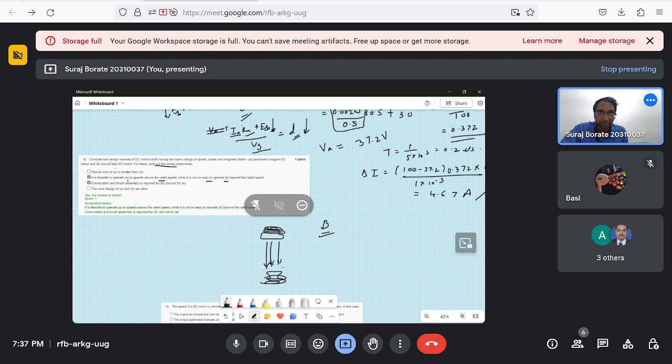There is also something called peak current and peak voltage, and then there's the rated or nominal voltage, and nominal speed also. This is the operating speed of the motor. Now, the speed of the DC motor is controlled till its rated speed by adjusting the armature terminal voltage by a suitable mechanism.